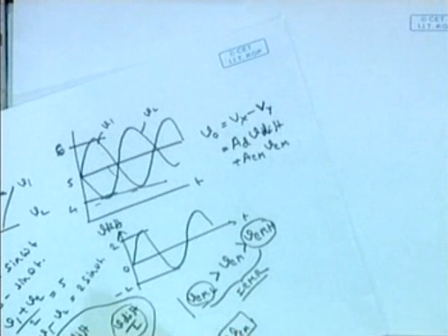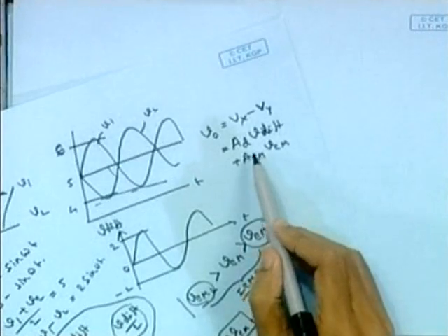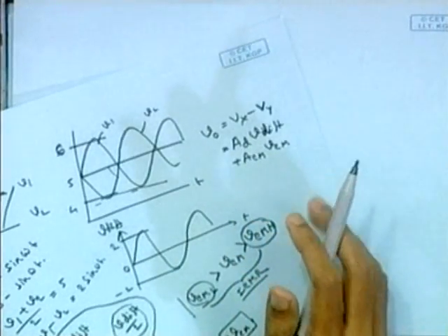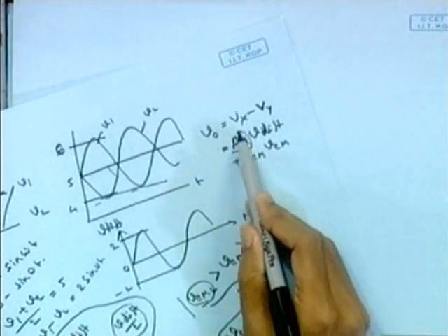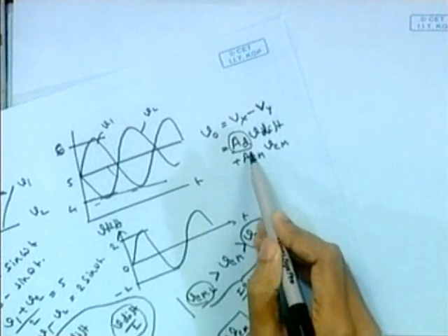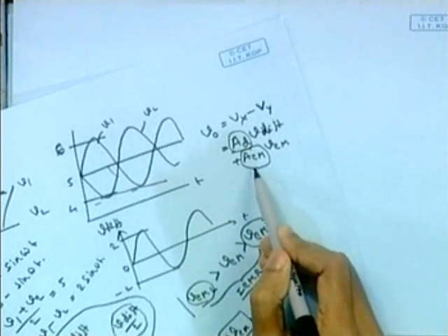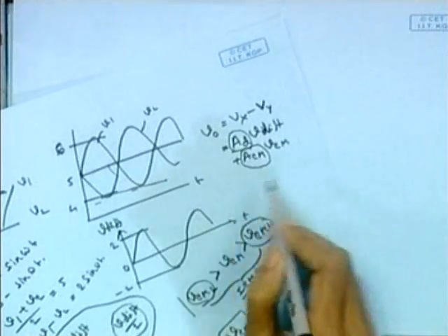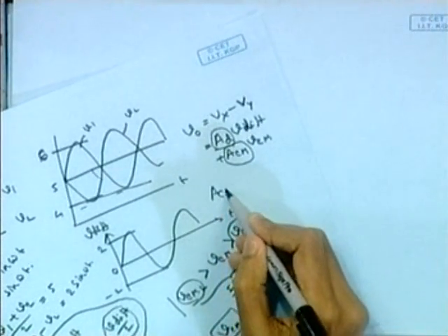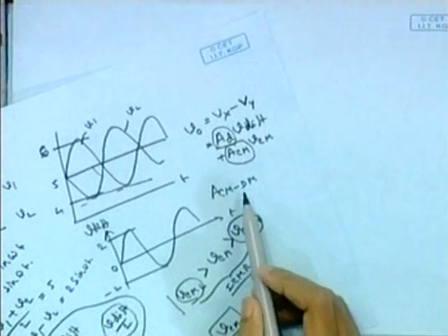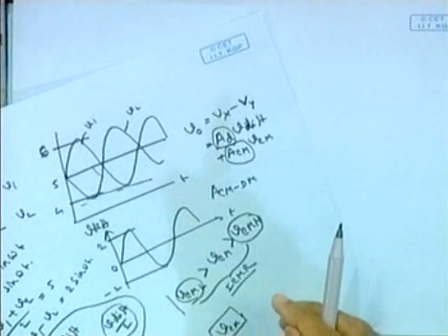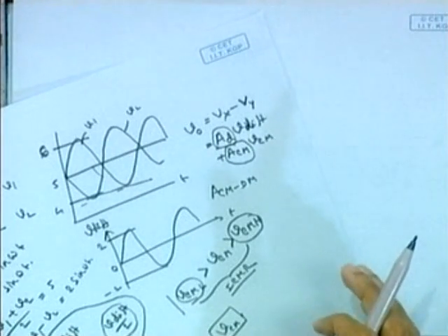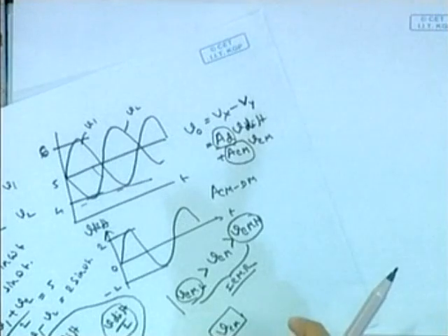Both the differential input as well as the common mode input will get amplified by our differential amplifier, and both of them will appear at the output. AD is known as the differential gain of our differential amplifier. ACM is the common mode gain. Actually this ACM can cause some confusion later. We should call it ACM to DM. What does it mean? If we apply a CM at the input only, suppose our differential signal is 0 at the input, we just give one common mode signal.